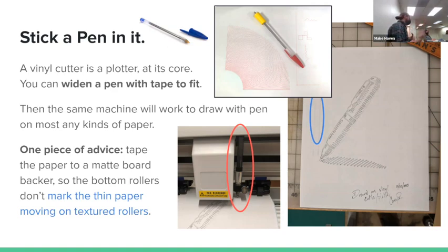So all those different features you'll want to take into account while you're thinking about how you want to produce it. The big machine's real win is the size, but it can also apply more force. It's got probably better precision. I feel better about its belt drive than the Cricut's belt drive. I was looking at our particular machine and I want to tighten up the slack in its belt, from having built other machines. But they're essentially the same. It's like big brother, little brother. And so that's what you're looking for.